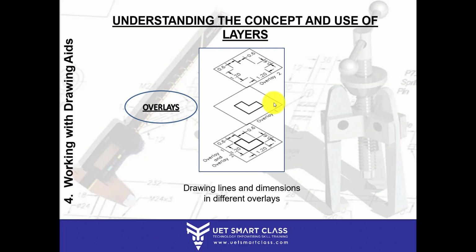I cannot overlap each and every section of my drawing. For example, take a layout. We know that we have to draw a lighting layout, a ceiling layout, a flooring layout, but still in an overall furniture layout or a basic layout, I cannot overlap each and every part of my drawing. I cannot show furniture and lighting and false ceiling within one layout. But here, with the help of layers, you can do that in AutoCAD. You can overlay your drawings.